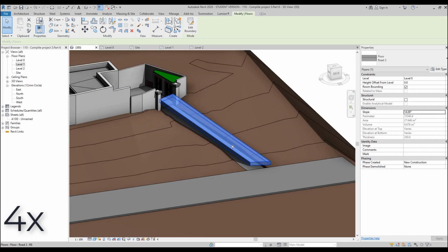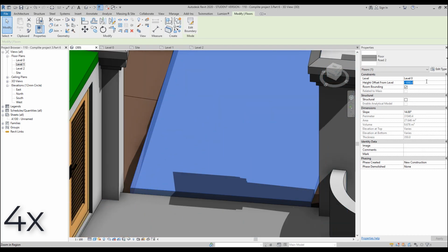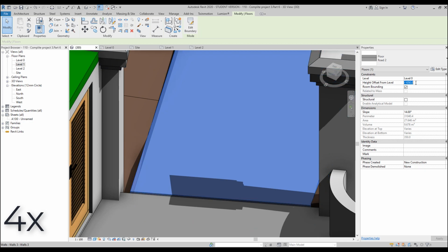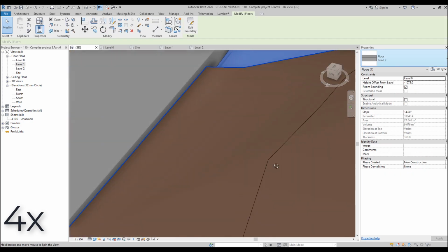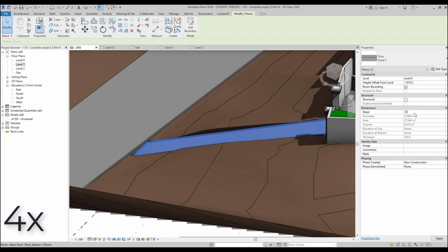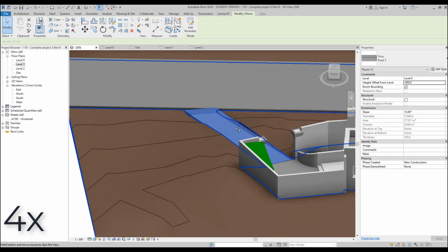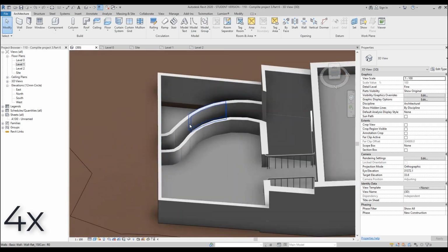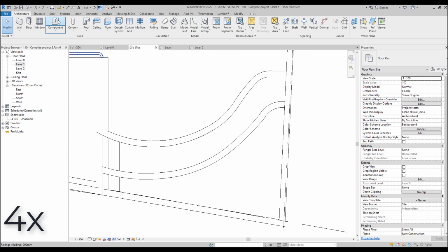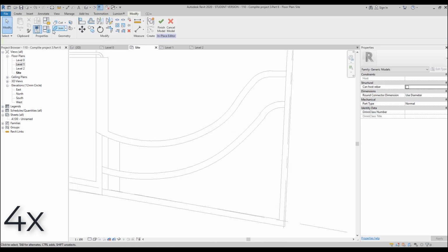Just apply your boundary, and after that don't forget the slope line and angle. It should be the same as your pad angle. So once you finish, just adjust it from one row to the other, and you will get a pretty nice result. Did you forget about these holes we have inside our pad?